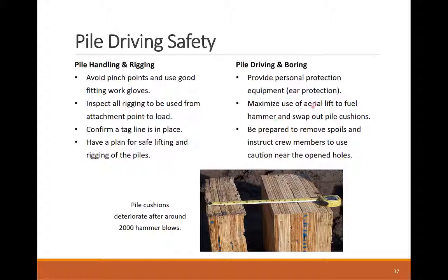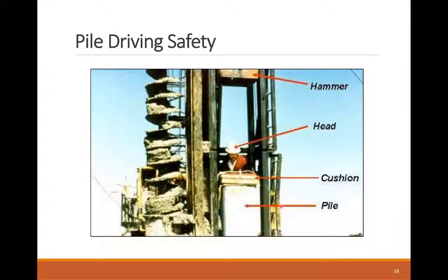Pile driving using hammers imposes more risk than vibratory drivers. For example, workers need to climb to high elevations to the pile head to replace the pile cushions or fill up the diesel for the hammering. In doing so, it's highly advisable to be aware of your surroundings, not like that worker here.